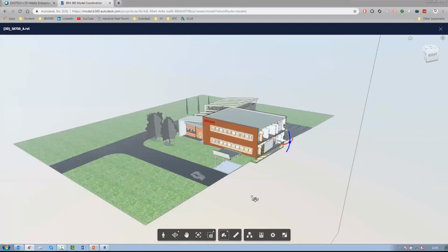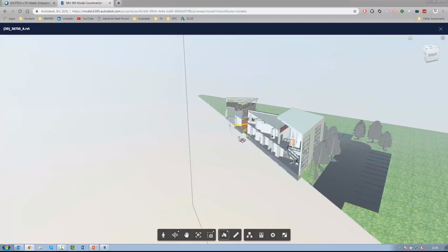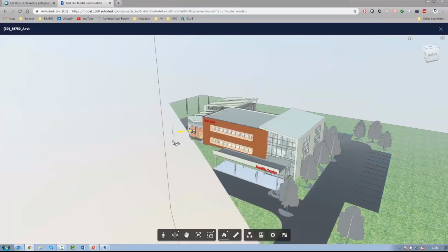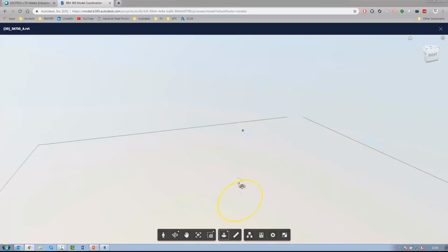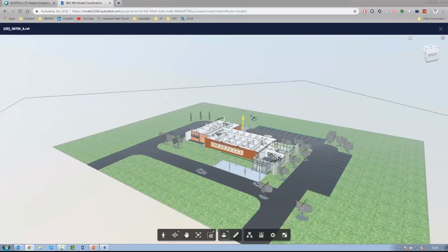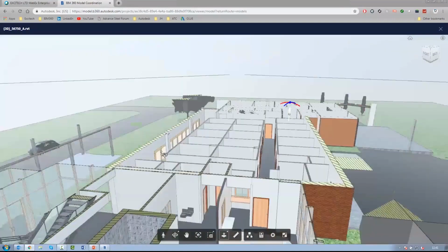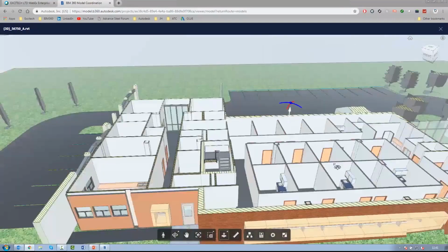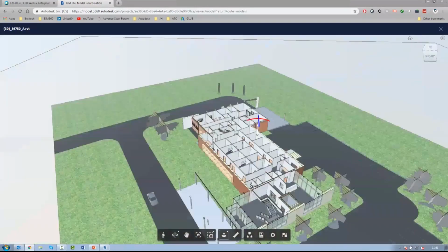If you've got a section in the X, you can section it in the Y as well, with the same functionality where you can pull sections through the model, and again the same in the Z. If I use the little arrow to pull that up, I can completely cut off the top and then go in and explore the model that way. So it's a really quick, really fluid way to explore in and around the model.